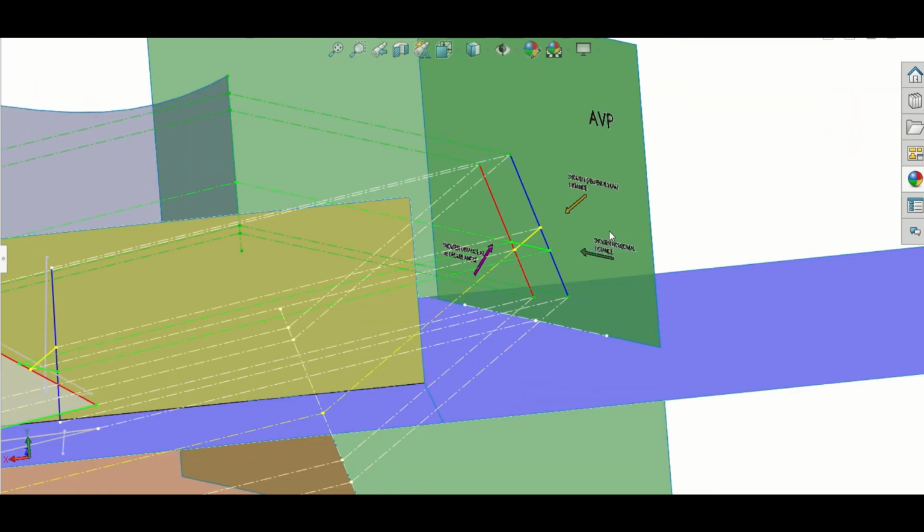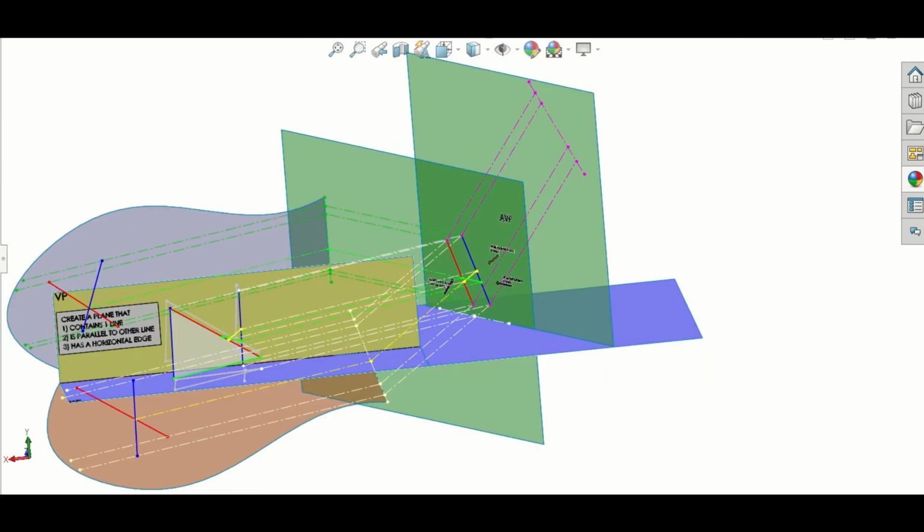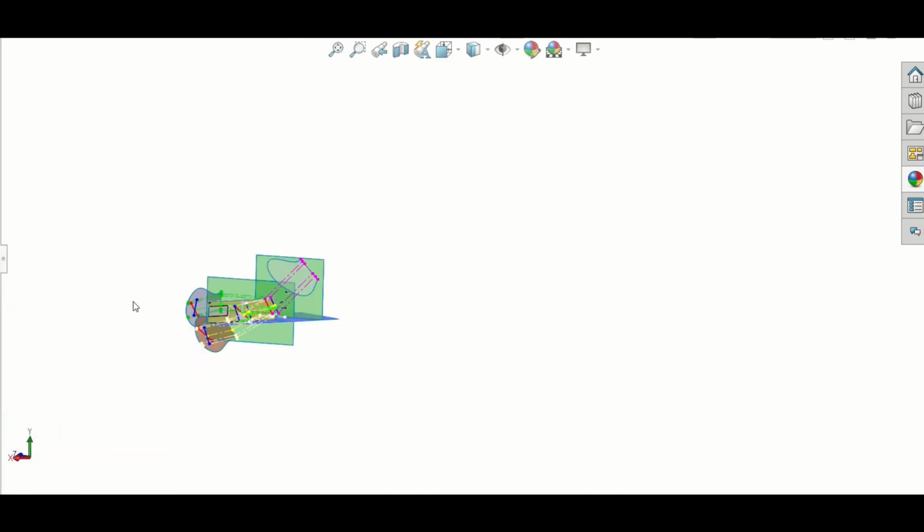And I'm really not going to spend a lot of time on this one because I think that it's probably going to be quite obvious what's going to happen. We'll view them. Everything is viewed based on the X1, Y1, based on the view that shows the two lines parallel. If it's asking for a 45-degree angle, draw a 45-degree angle based on the ground. Up at 45 degrees and put in your plane. And that's it really. We could stop at that now and you'd probably just get the rest of it and be able to draw the rest of it, no problem.